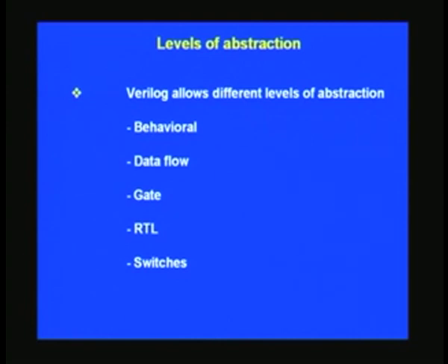And for those who are used to gate level simulation as in schematic entry earlier, they can still use gate level primitives, and if you want to get extra timing closures, probably you may have to use gate level primitives as well. And the next most important thing is register transfer level, and it is called RTL. This is the core of digital design, and if you violate RTL, the synthesis tool will promptly reject it. This is only to ensure that the final product that you are going to tape out will really work on the hardware that it is meant for.